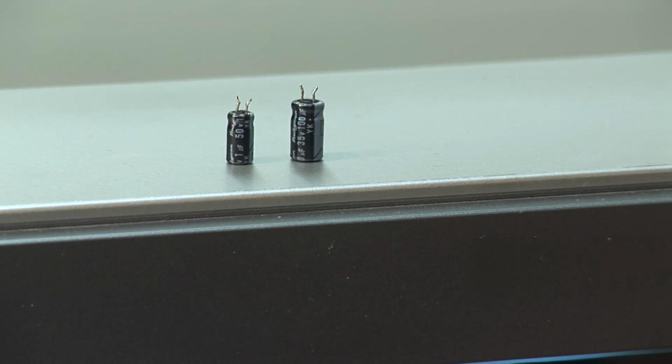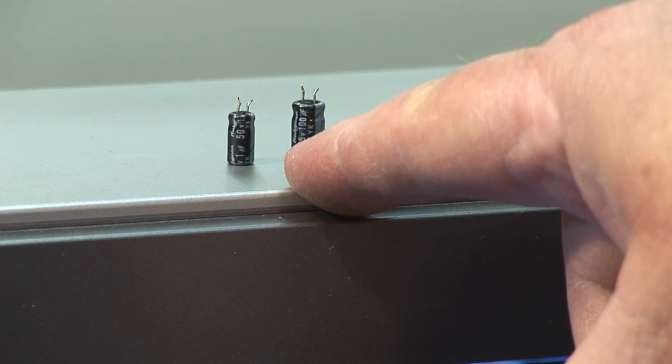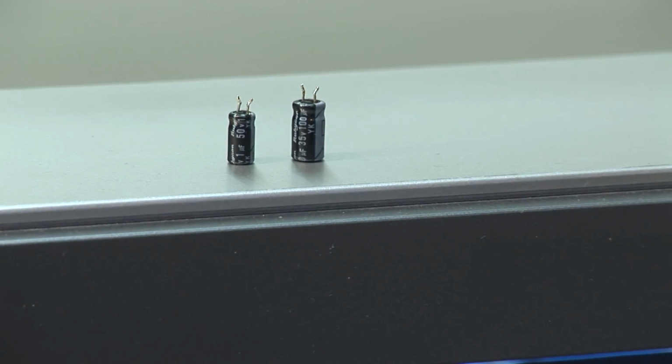There's the 2 problem caps there, C407 and C408, a 1 microfarad 50 volt and a 100 microfarad 35 volts. Both of them were just standard 85 degree capacitors. I did replace them with 105 degree. A lot of the older Toshibas, these capacitors were red in color. And the red ones in some of the older ones were actually a special cap at the time. And you had to order them from Toshiba. That was because that was back in the days when 105 degree low ESR capacitors were not common.